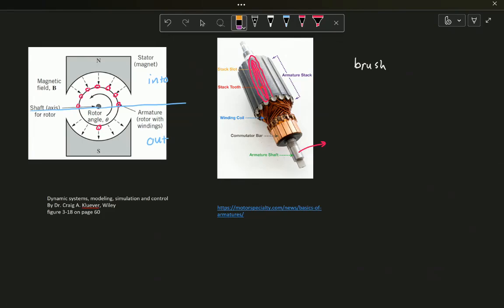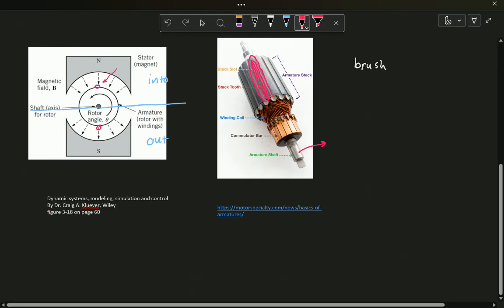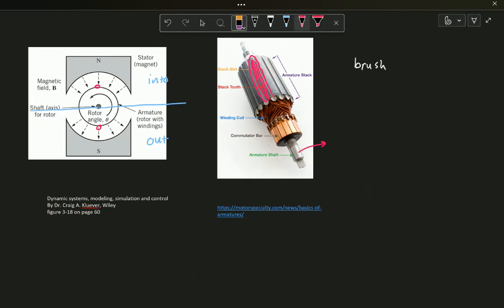We're going to use the three laws that we discussed. Imagine, let me just get rid of all these wires and I'm going to keep only two of them. When I apply a current on this specific wire, because of the first law, I'm going to change that wire to a magnet. And since I have an existing magnetic field from the stator, now the second law kicks in, and I see that I'm going to have a force applied on that wire.